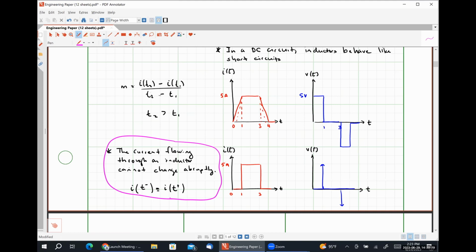The reason why those sparks are being created is because when you change the amount of current flowing through your device by rapidly unplugging it from the wall, if that device uses a relatively large inductance, it's going to generate a voltage across its terminals so large that it's going to literally ionize the air.